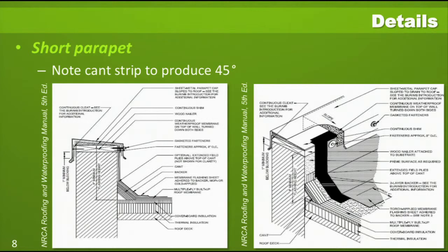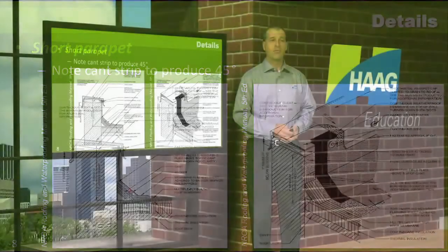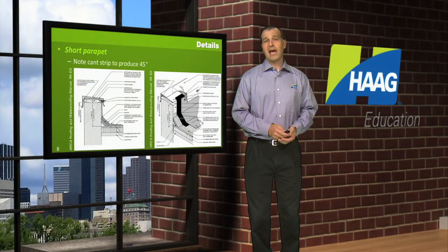After priming it, another single-ply flashing material that could either be modified bitumen roofing or a fiberglass roll roofing material would be installed going from the flat portion to the cant strip up the vertical part of the wall and then be fastened near the top of the wall. The top of the parapet is covered by metal cap flashing, also known as coping.